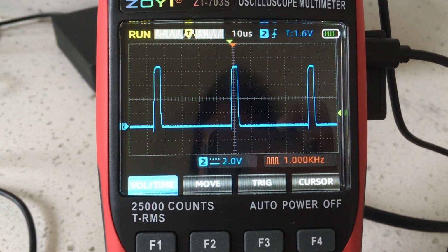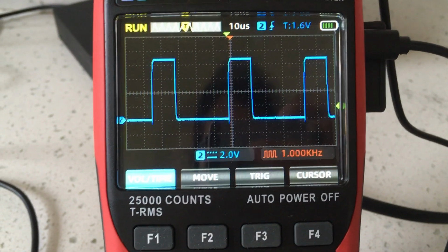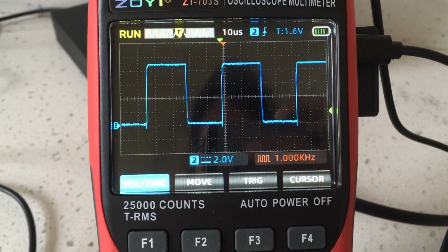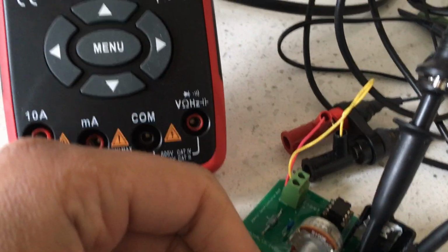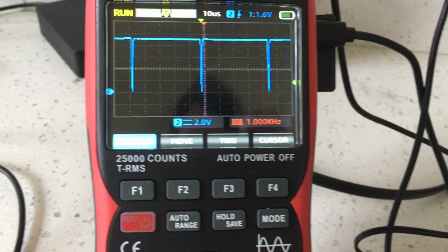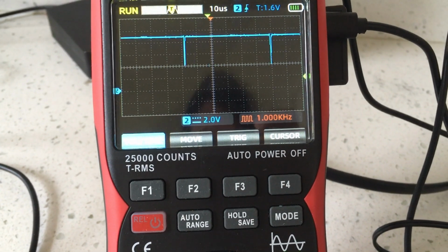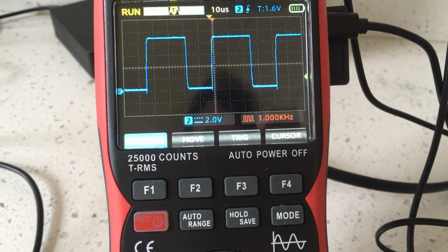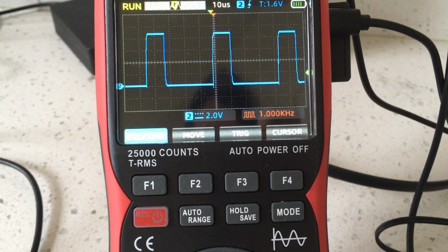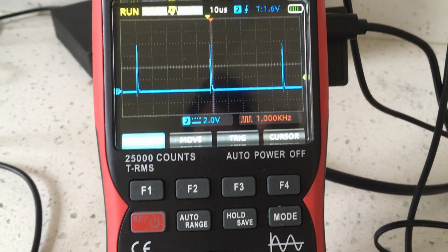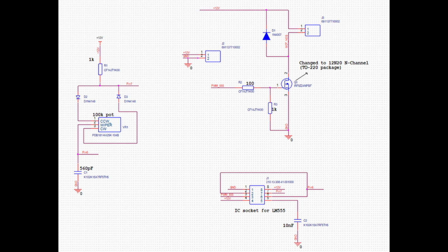What does this wiring structure give us? Well, it gives us the ability to independently control the charging and discharging times of the capacitor, and hence the duty cycle of the generated PWM pulses from the 555 timer without changing the frequency. Thus, the potentiometer will serve as a simple knob to change the speed of the motor. If you wish to generate a different frequency in your project, try using different values of C1, say 1 microfarad or 5 microfarads, and test the output at pin 3.